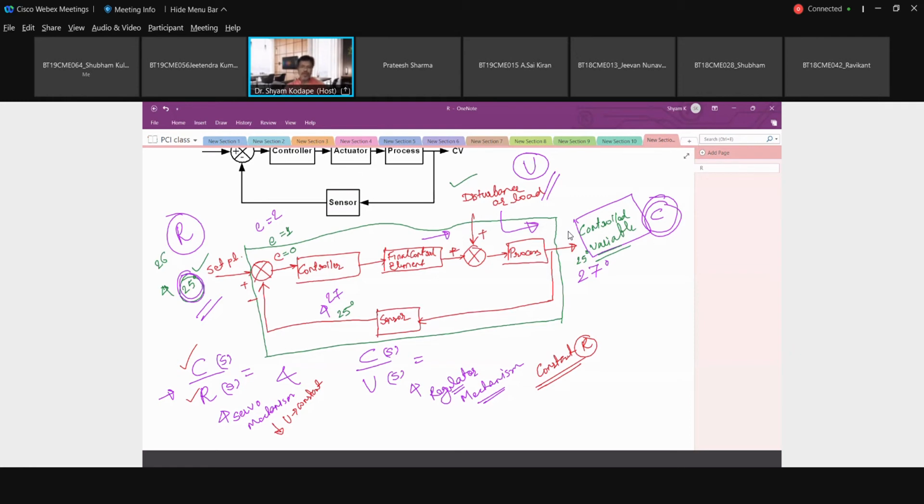So now we have to manage all of these. Just like we kept two tanks in series, similarly the controller and final control element are in series, right? Both are in series. So similarly, we will identify the overall transfer function, and the nature of the overall transfer function will decide how that control variable will change based on the conditions, whether it is a servo or a regulator.